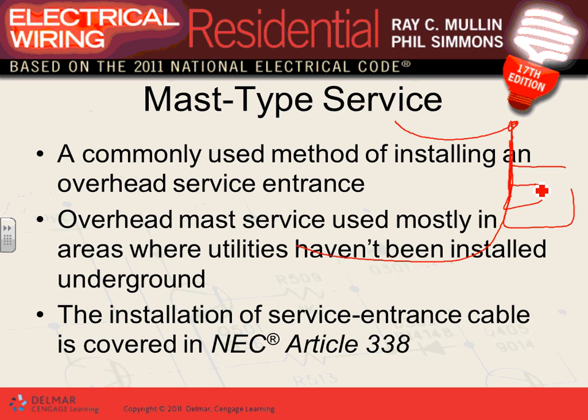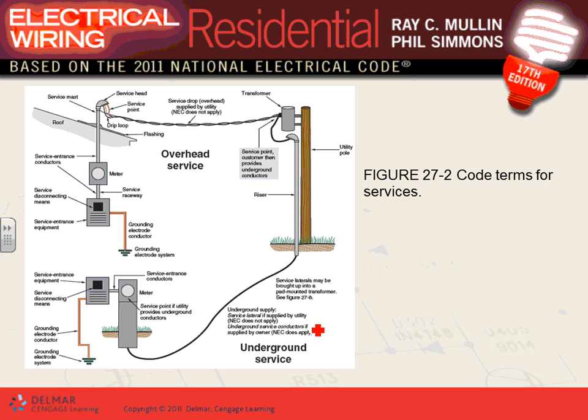Service entrance conductor, guys, is a special type of cable, and it's in Article 338. It's like NM cable, another cable you see. They bundle together two insulated conductors with a bare conductor. The utilities use it to bring the power into your building.